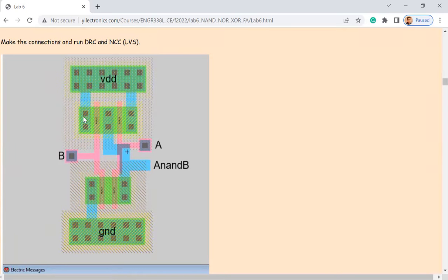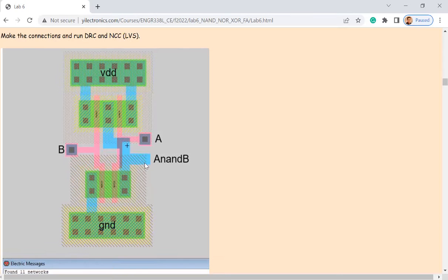So what I did is I connected these 2 nodes to VDD and introduced the middle layer here, and I put an A here. Why put an A here? I should put it on the left, but that's okay. So that's output, right? It won't cross the metal 1, actually. Yeah, poly over metal 1, yes.